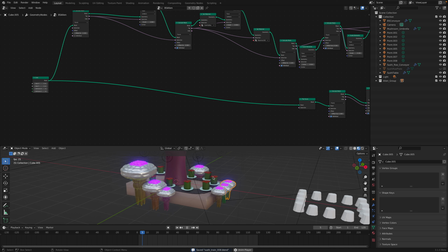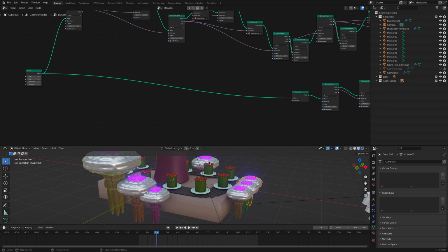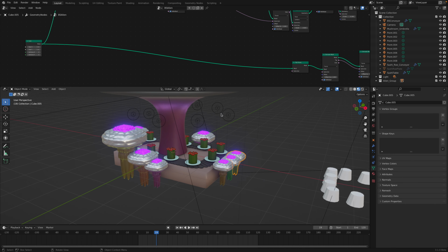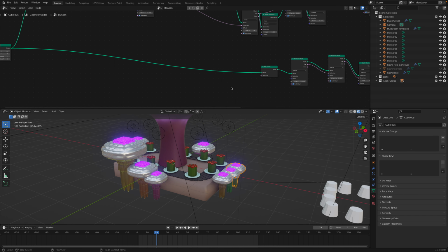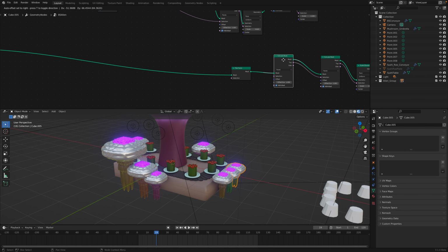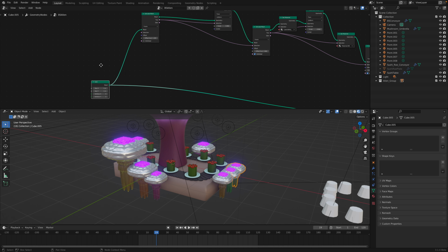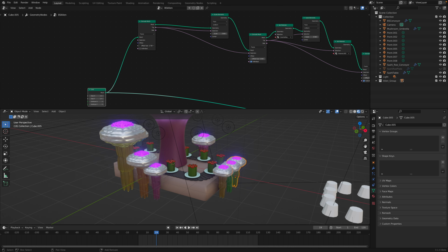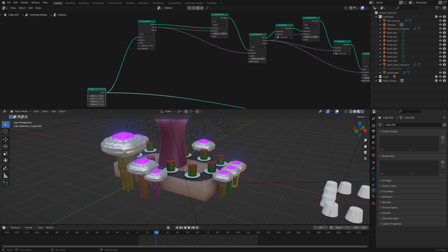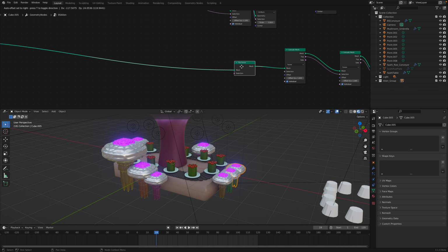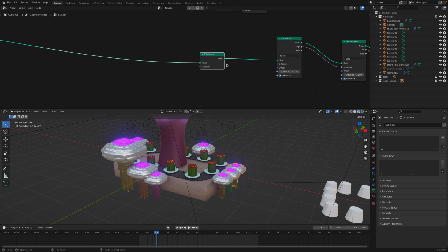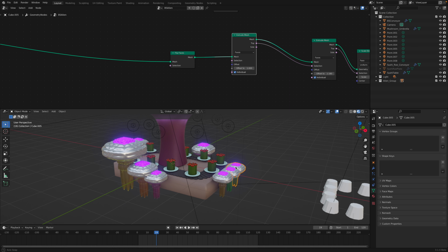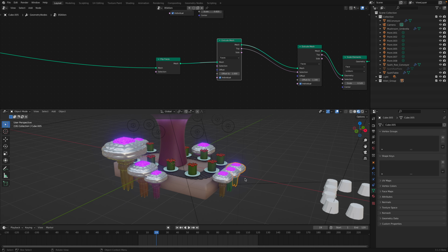Yeah, but I think the whole thing, I did create this blend in a few hours, maybe an hour or less or more. So you can see here, the top part is simply like the mushroom, extruding it, but the bottom part is because I flip the face and then extrude it down, and then I merge everything, so it's back to a single surface.